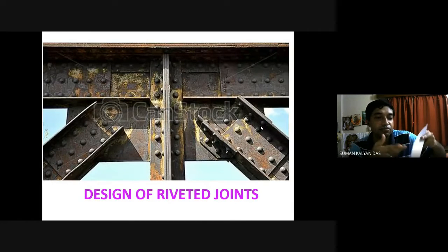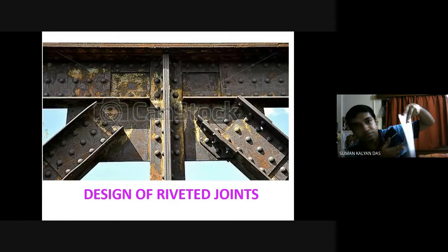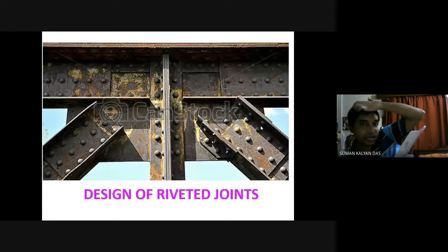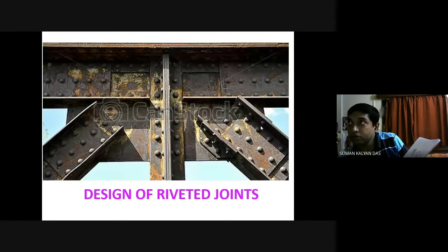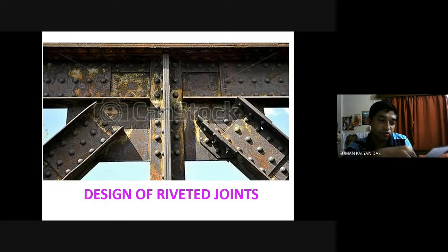Obviously, in that case I have to get the cross section. Everybody knows the cross section of this particular plate, and suppose this material is stainless steel. Its strength is well known. You get the standard tensile stress values, ultimate and yield. So those values are known. You multiply them by this cross section, and you get the maximum or failure load of this plate if it had been continuous. You are able to get it, right?